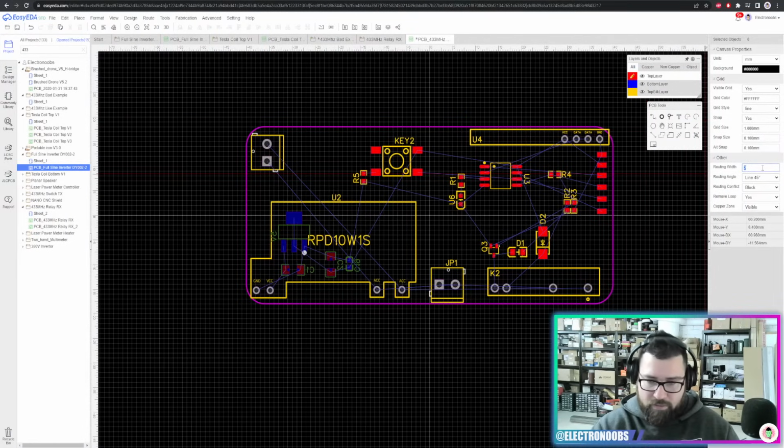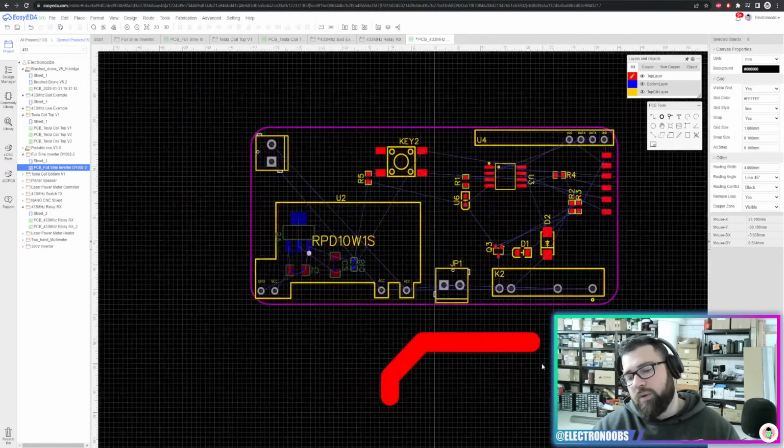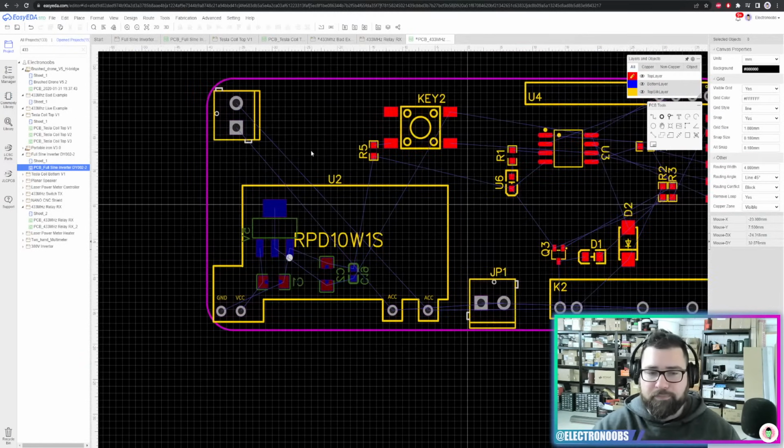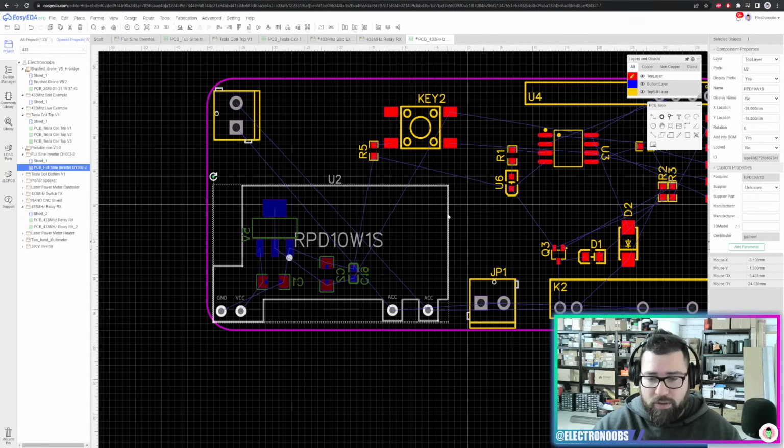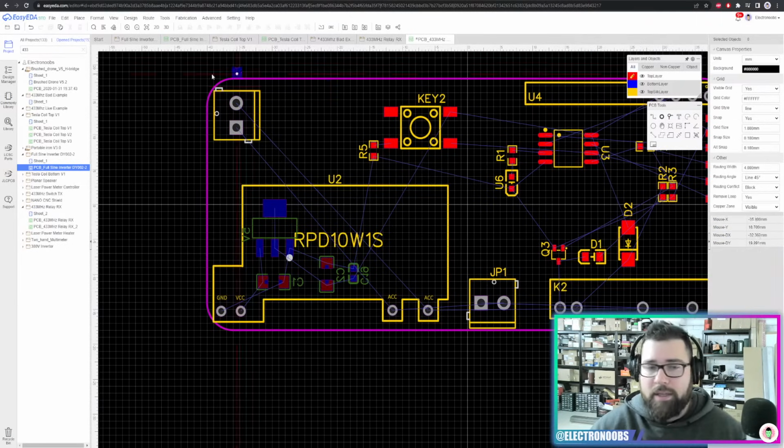First we start with the power connection, and I really want the power connection to be 4mm, and I will leave the angle at 45 degrees. You can change it to 90, but it is a lot better to make it 45 degrees, especially when you are working with high frequency signals. So the first part, I will connect all the power, from this connector to the regulator and to the output. So we start with the track, we select the top layer,